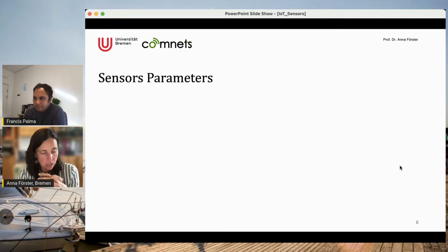Sometimes the microcontroller has some requirements on which pins have to be connected to digital inputs and which to analog inputs. Typically, however, this is a designer decision of the platform itself. I don't remember by heart what the pins were, but in most platforms you have a specification by pin, which ones you can use for analog inputs, and which ones you have to use for digital inputs.